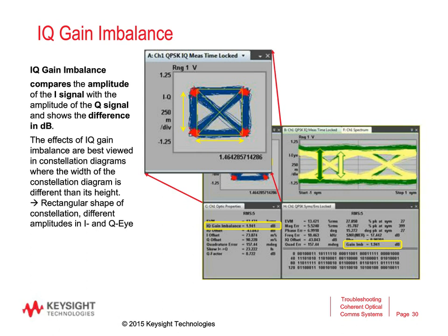Also, this imbalance could be seen in the eye diagram of a signal that we see on the right-hand side here as yellow and green eyes. You see that the green eye or the green signal is slightly higher than the yellow signal, corresponding to the signals in the constellation diagram.